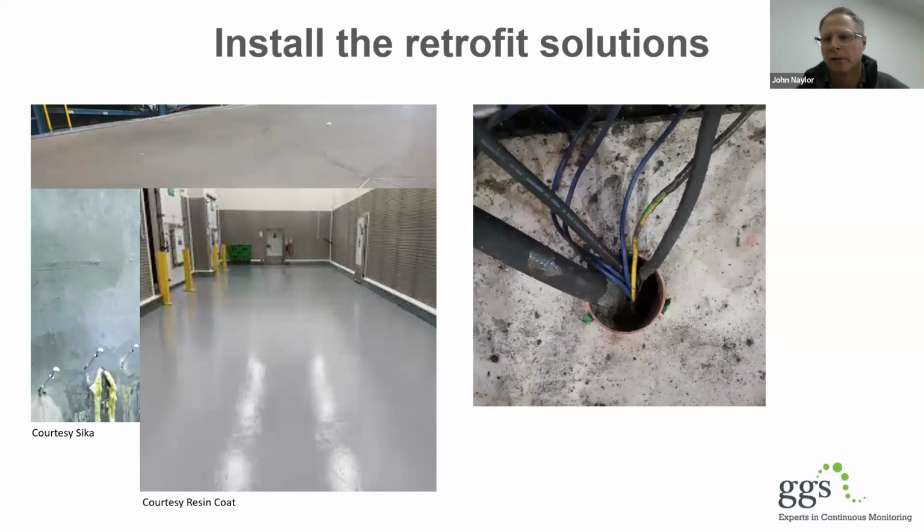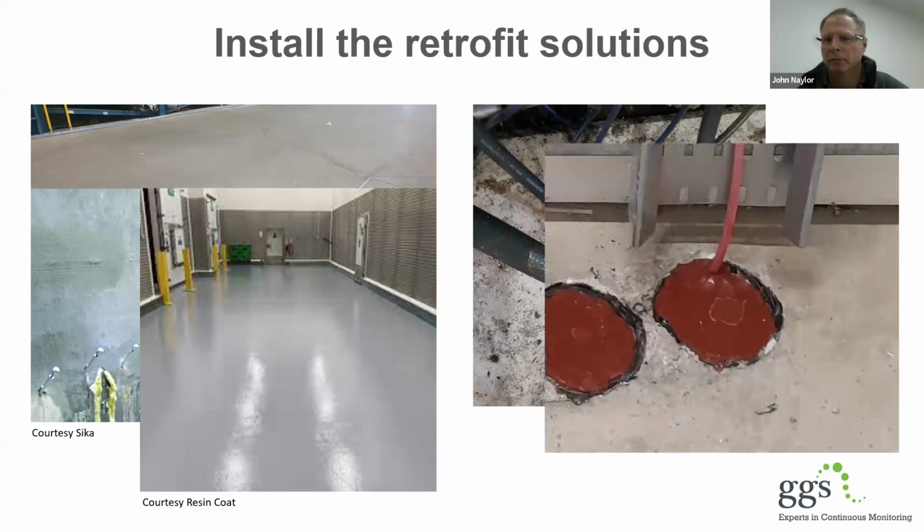The other obvious source of ground gases, other than cracks, is ducting. So here's an example of a duct. Lots of services coming in, probably, but I don't know whether this did have ground gas protection or not at the time. It might have done. But it bypasses that membrane if there's one there. It's not been sealed. There's probably thousands of these things lying around in the UK. Get it sealed. It's not difficult. There's an example that we can do and it's easy to apply.